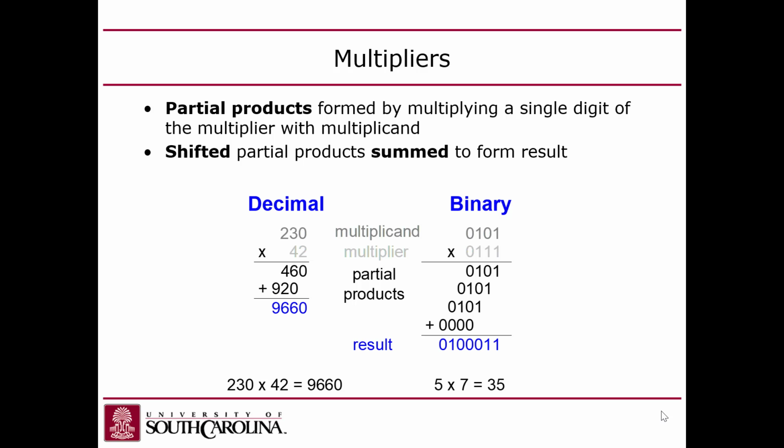We're going to call the first number there the multiplicand, and the second number the multiplier. And it doesn't matter which one we assign to which label, because multiplication is commutative. So this 3, we can shift it and multiply it by a power of 2, but then we can do that for multiple powers of 2 as represented by the 1 bits that are in the multiplier.